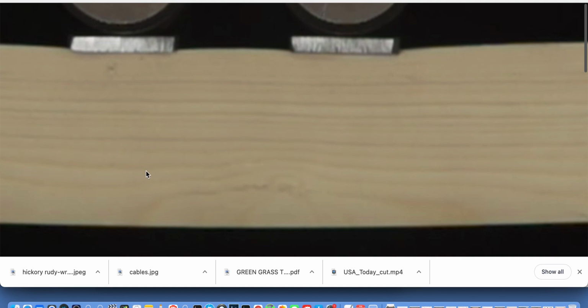And right here, all of a sudden, our rebar gets a little funky. The profile of the rebar comes down, goes up, comes down. So down here, all of a sudden, we just lose our rebar. No rebar at the bottom. It's just a big chunk of concrete, if you will. Our last piece of rebar is here. Our last piece of reinforcement. This doesn't even count as rebar because here's the rebar. They just sort of grabbed a piece and threw it in the ground.